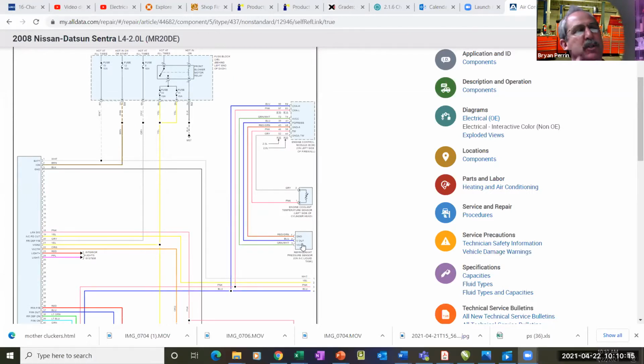But your pressure switch, if that's a supported PID on your scan tool, that's a great place to start. And you can see what? It's a 3-wire connector. So what does that mean? Power, ground, signal return. It probably uses 5 volts as a VREF, but who knows? But you're going to have a ground, a voltage reference, and a signal out.